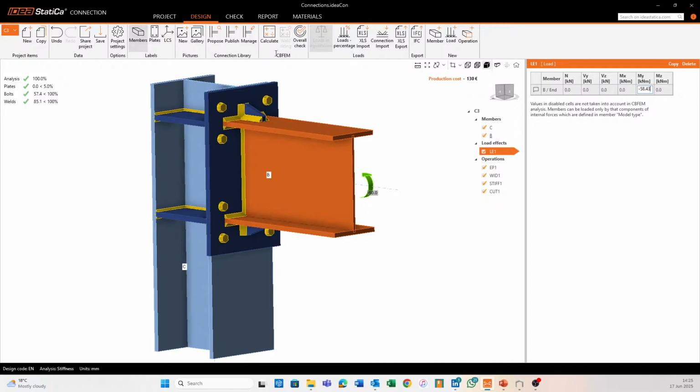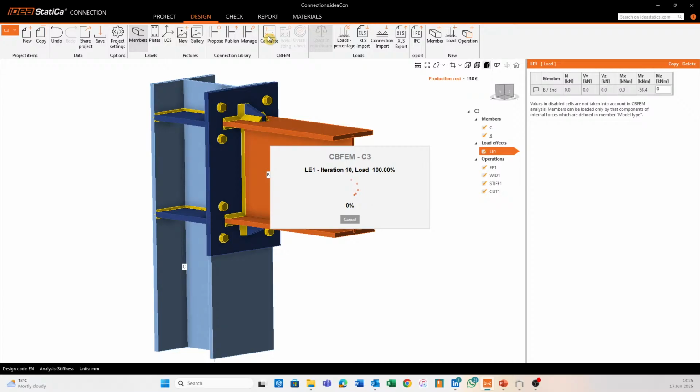So cool. When there's a change, now with these new values, instead of reading off the initial stiffness values, we read off the secant values, and then we start this whole process from scratch again. All right, so you can see now, as we work through this, there's a good reason why this isn't necessarily incorporated holistically in our design workflows. And that is because it becomes an incredibly complicated and iterative process.